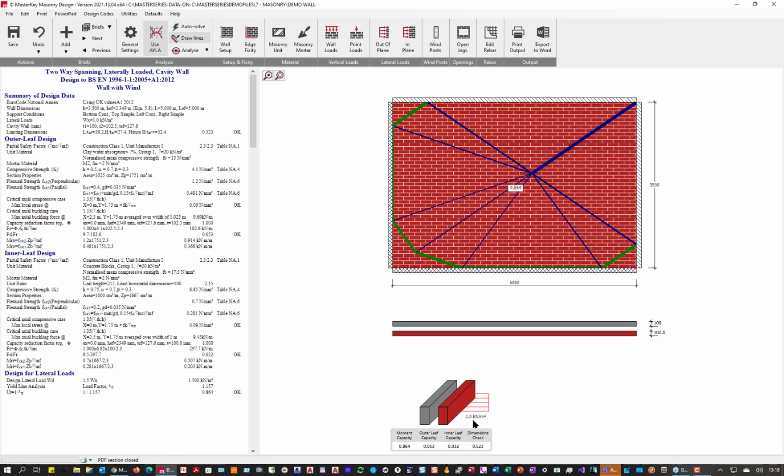And our lateral load is 1 kilonewton per meter squared. Pretty typical wind analysis, and certainly in the lower regions and Midlands. Up in Scotland, I was playing with a guy there earlier, looking at wind analysis, and we were in, where was it? Islay, and we were at 3.5 kilonewtons per meter squared. It was a bit scary. So that works. Now let's look at the next wall.